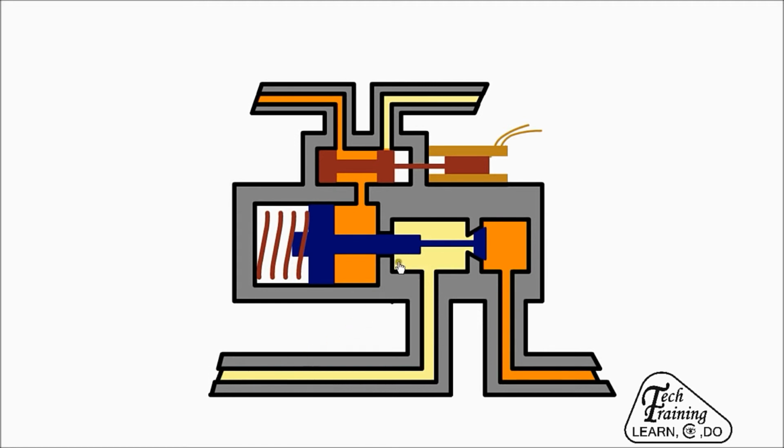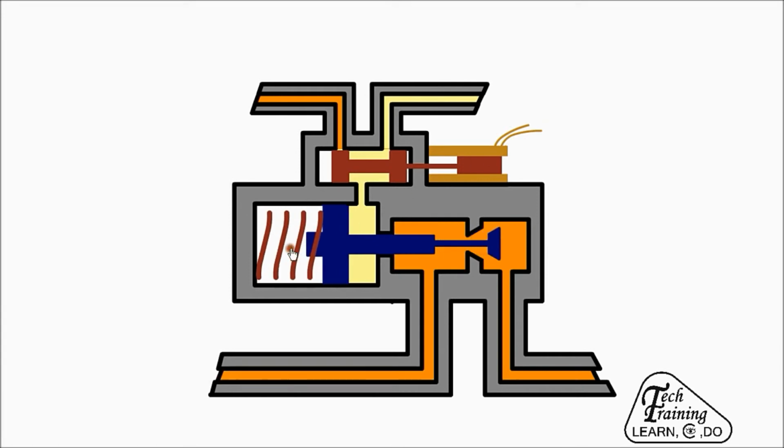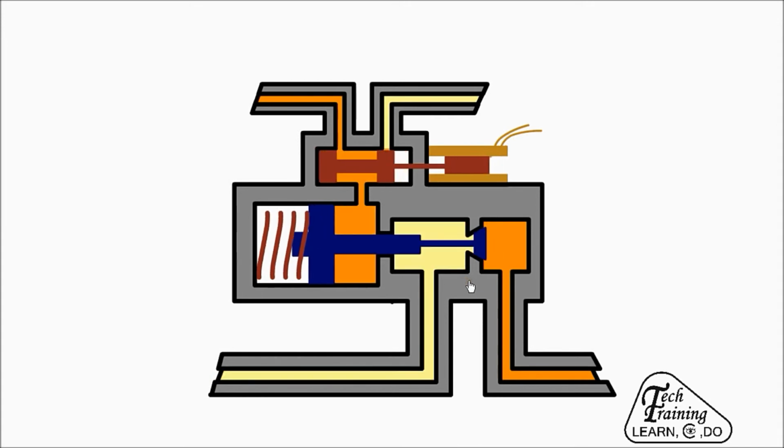releasing the brakes. When the solenoid is de-energized, the high pressure fluid is released back to the reservoir. The spring force opens the valves and the additional rod volume also increases the fluid pressure and reapplies the brakes. This cycle can happen 20 times per second and results in the pulsing sensation in the brake pedal.